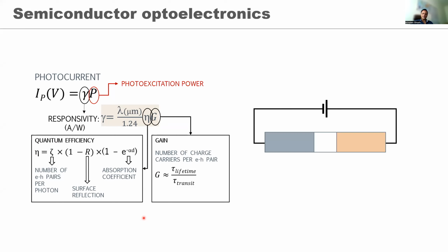What gain is, is very simple to understand. Suppose you have a PN junction diode, you shine light and you create an electron hole pair in the center. Because there's an electric field, usually when you shine light and create an electron hole pair, the hole remains localized, and the electron can move around. So the moment electron hole pairs are generated, the electron rushes towards the positive end and vanishes into the battery, and another one is generated.